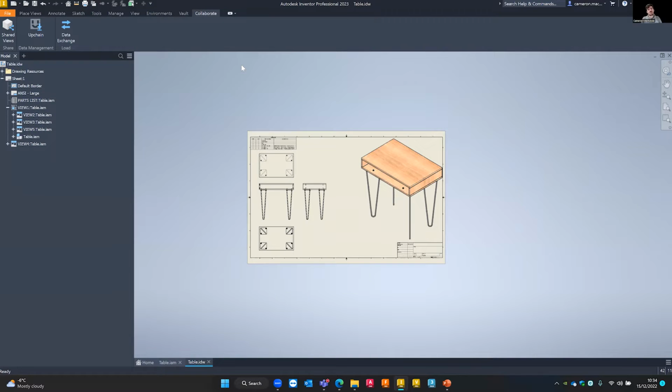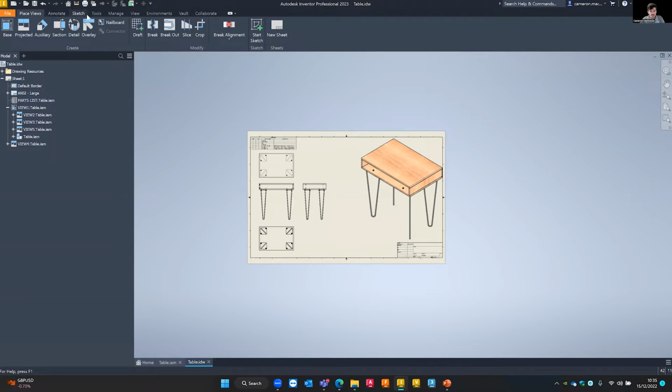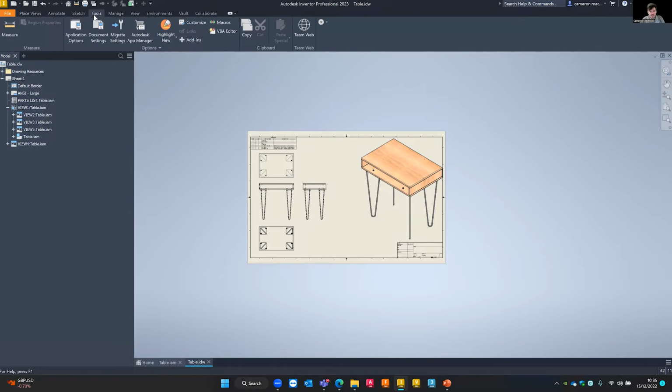And now, if you're using the likes of Vault Professional, you've got the ability to print to PDF from inside of that, so you can convert any file into PDF as well during that process. So we've got various ways of going through that and being able to share our information from there. Otherwise, we could just send the raw DWG file, or we could push out a DXF file as well as part of the process.